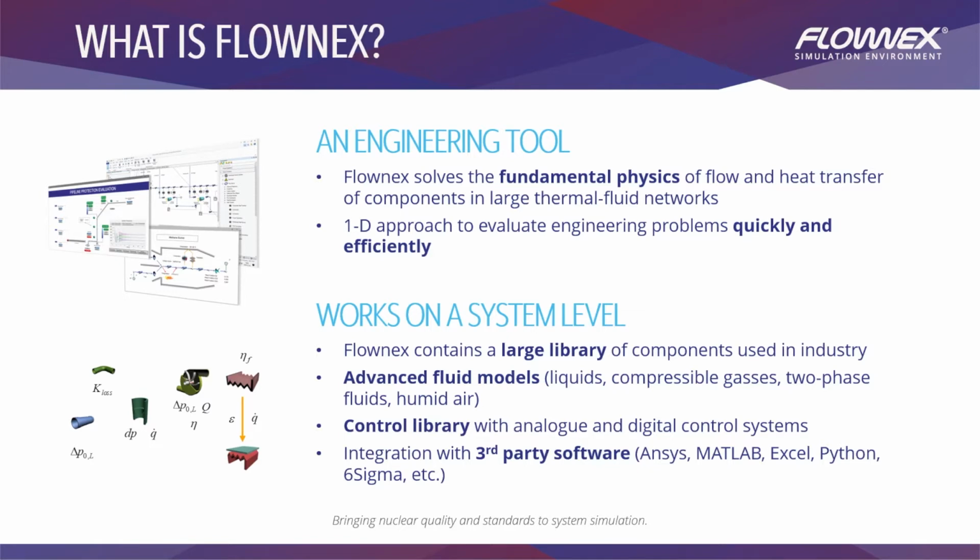Flownex has both a steady state and a transient solver, and along with our transient solver, we also have a library of control components that can be used to model both analog and digital control systems that control the entire system. This is very useful because it allows you to simulate the process itself as well as the control system to understand how the true performance of the system would be.